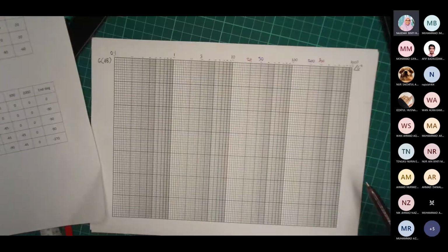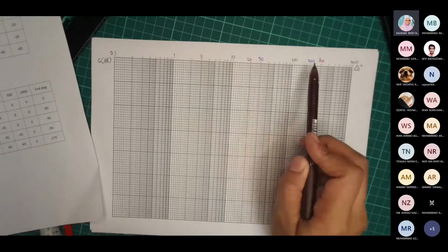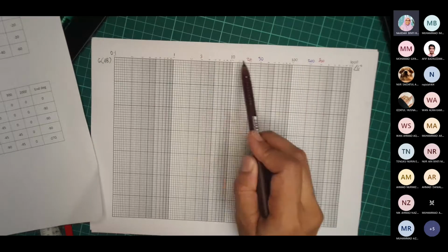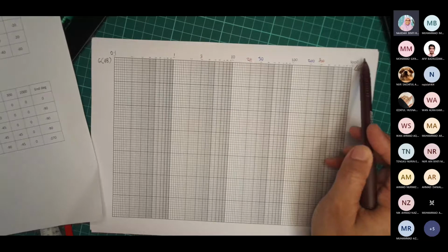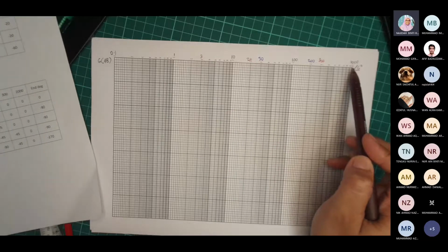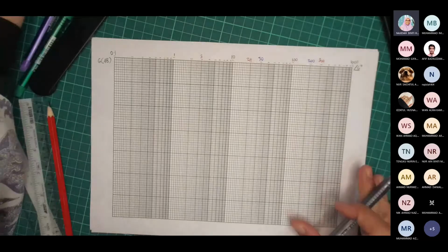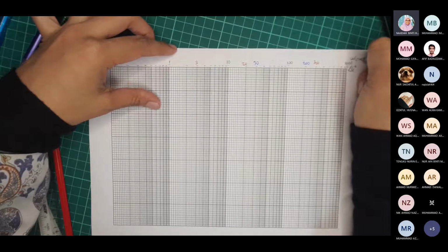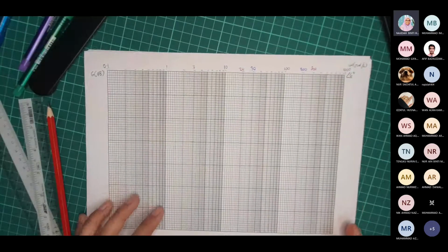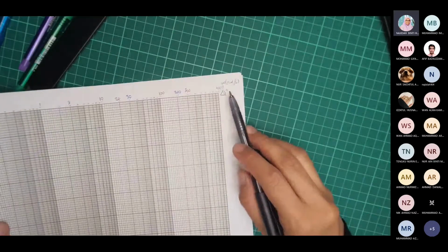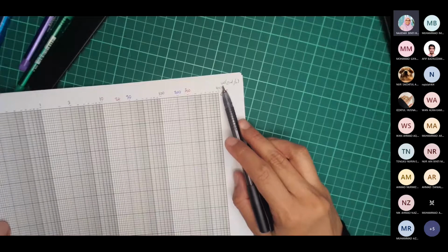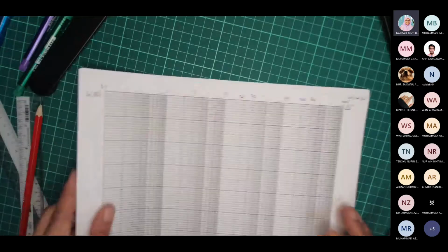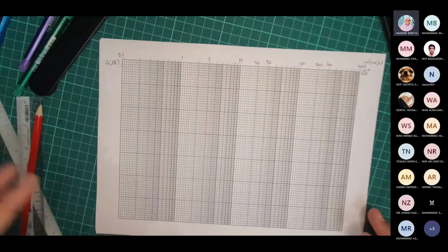So we have labeled both of the cutoff frequencies 30 and 200. We have labeled our minimum and maximum frequency range from the phase table: 3, 20, and 300. The 2000 cannot be labeled since our maximum frequency is only 1000 radian per second. For the x-axis, you should label it as omega. The unit is radian per second. So this is how you label your x-axis. Omega for frequency, the unit is radian per second. Done labeling the x-axis scaling. Any question?